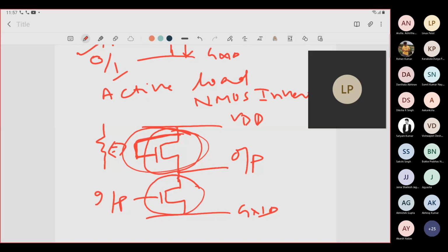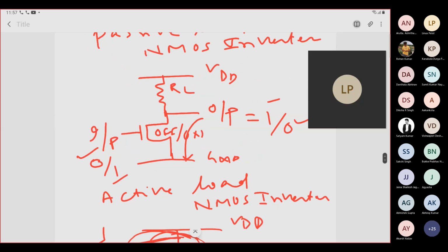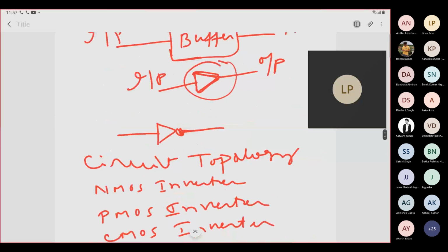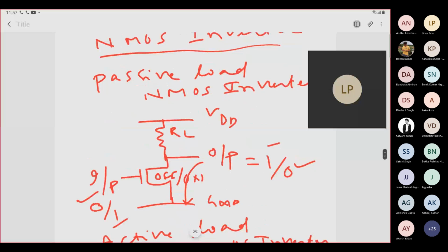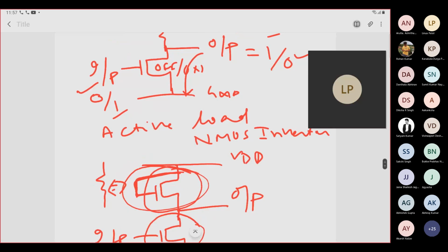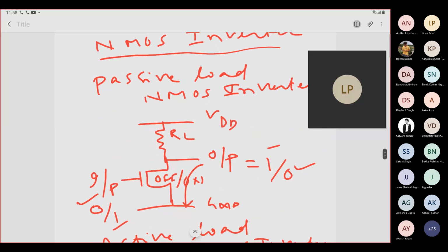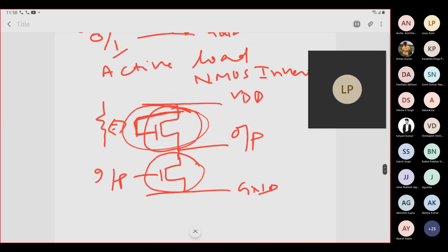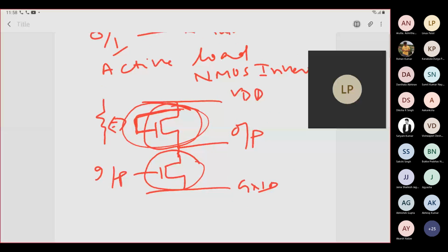If you go with a passive component, that passive resistor will take a larger area compared to an active resistor, and it will also take a lot more time to fabricate. So realizing the active resistor means you are minimizing the fabrication steps and the time.